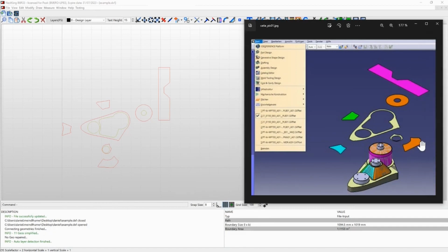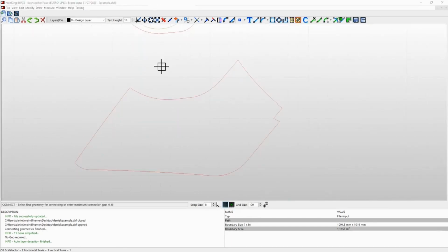So the line we want to offset is this one, which corresponds to this cut here. So there are several possibilities to offset this line down here. The first one I would call the AutoCAD-like approach. Therefore, we first have to break this geometry into pieces like this, and then we have two geometries. And this down here is the one we want to offset.